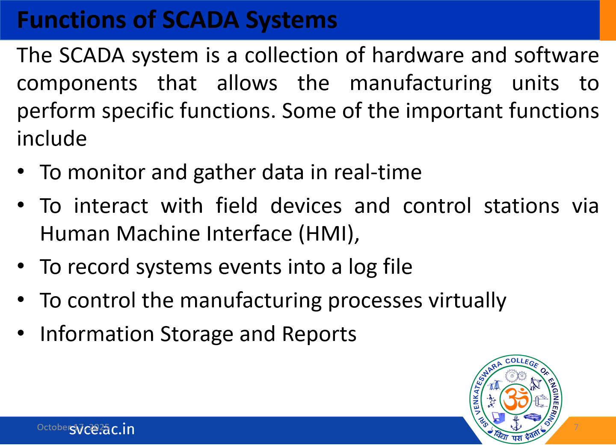Based on alarm supervision and management, SCADA systems are used. It uses alarming features that come along with the software development. Configuration of systems can be done, and the configuration of the alarm is very important here. We can consider two types of alarm systems. The first type we call system defined alarms, which are managed by the system itself, and the second are user defined alarms, which are managed by the user.